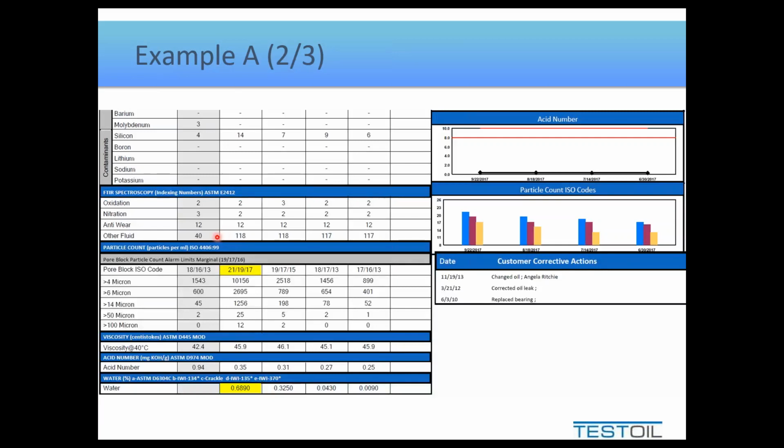So the difference that I'm seeing here would, at first glance, suggest there's a contaminant in this product, 2 different fluids mixed together. But again, reading the whole report, I look at the history and go, no, the baseline value in this, which was brand new oil, is pretty much the same as where we are right now. So again, I don't think there's anything abnormal in that data. I just have a second reason to question this new oil column and think maybe it's not entirely up to date for my current oil.